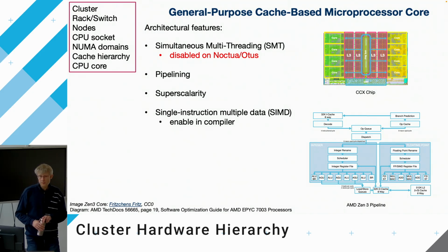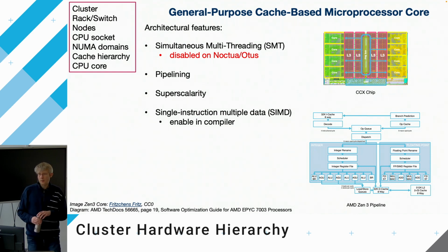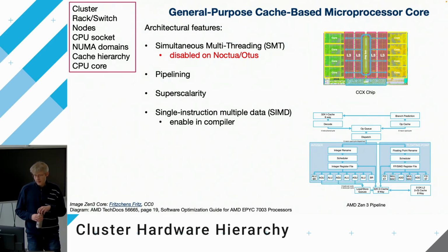For this, you need to have more resources, more execution units inside of the CPU, and also the memory access needs to support this, to feed the CPU with enough data so it can actually perform all of these calculations. Else you would have the resources inside the CPU, but would wait for data until it arrives, and then you have basically unused resources. So the complete CPU has to be adapted and enlarged with resources to have an actual performance increase.